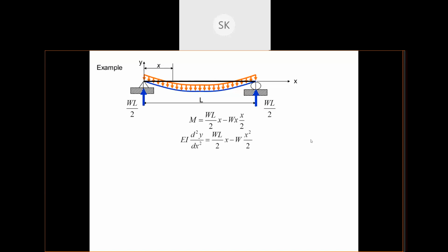Slope is maximum at the end support, and slope deflection is okay. See, at supports the beam is pinned down, it has been hinged. So at A and B, at the supports, your deflection is very less. If you see the curve, there is no deflection at the support.